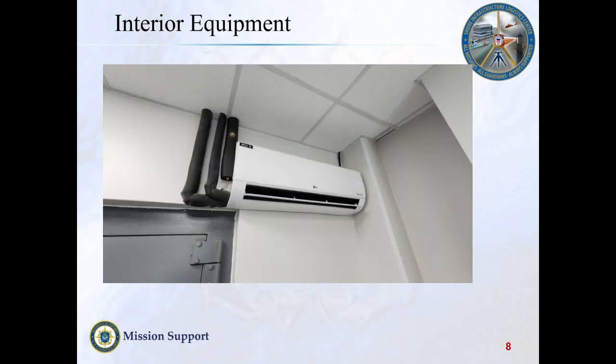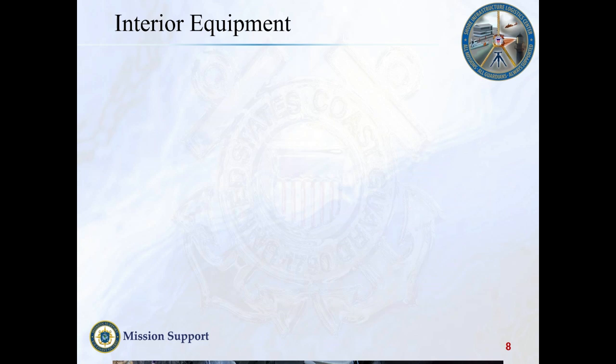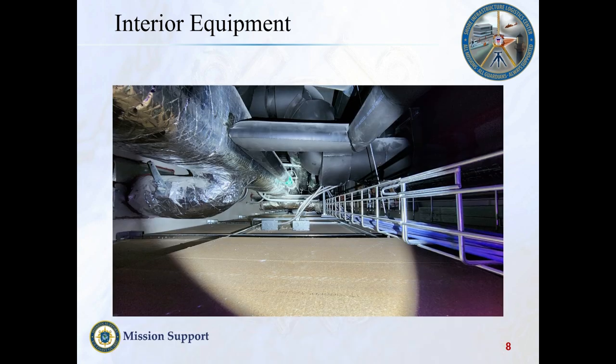Suspended acoustical tile ceilings are extremely common, and you'll need to poke around above the ceiling looking for HVAC terminal devices such as fan coil units or VAVs. Also be on the lookout for exhaust fans, especially in the bathrooms, locker rooms, kitchens, or galleys.